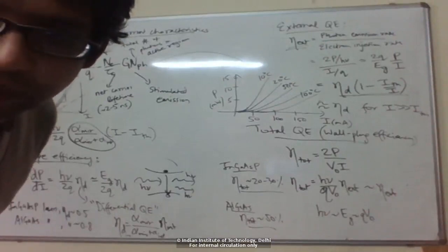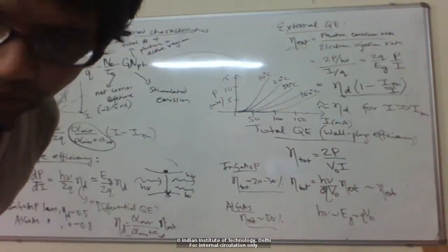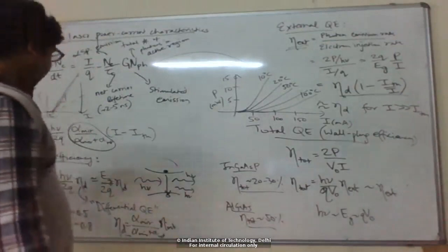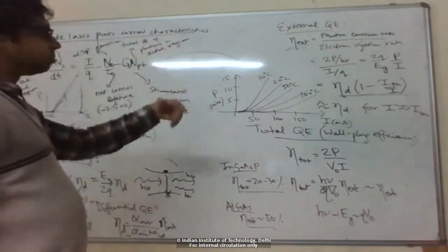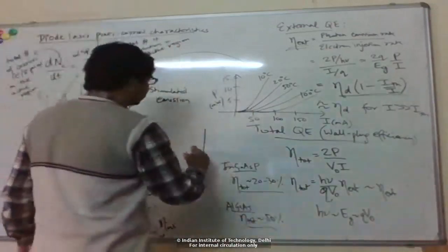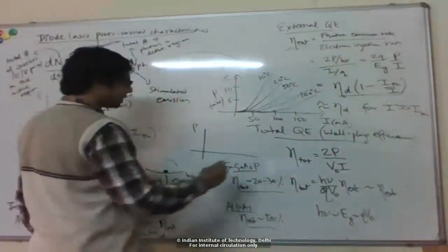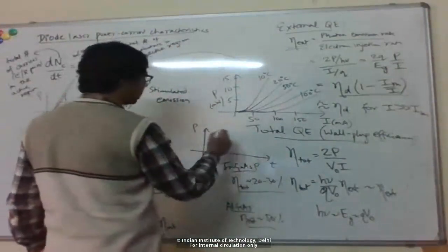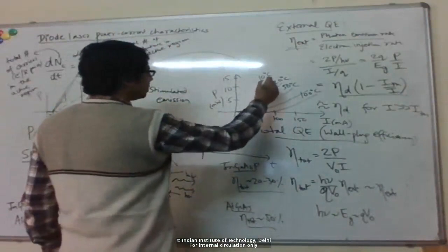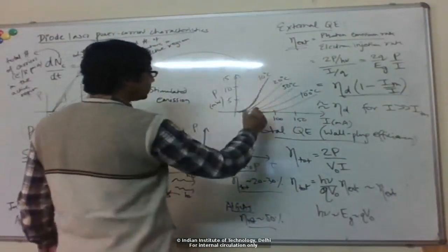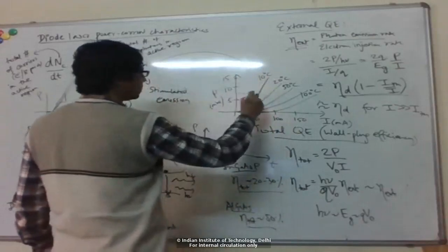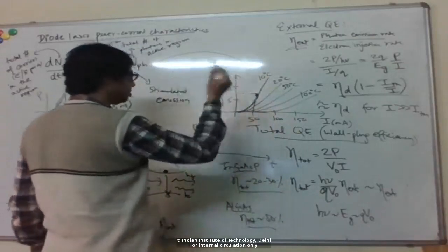Neglecting the spontaneous emission is neglecting optical noise. Yes, you're right. Spontaneous emission is basically like noise, right? So for example, if you measure the power coming out of the laser as a function of time for a particular set current, let's say I operate the device at 10 degrees Celsius, set the input current to some 50 milliamp, I should get out some, say, 7 milliwatt.